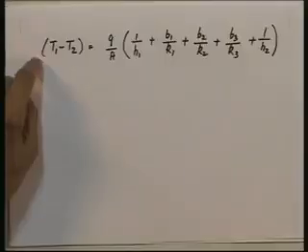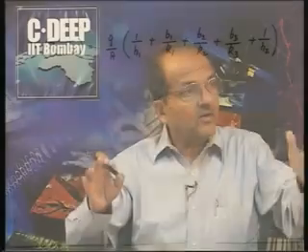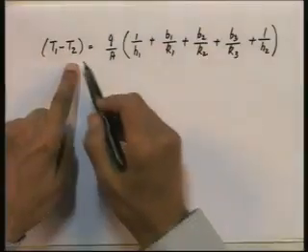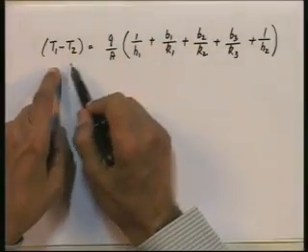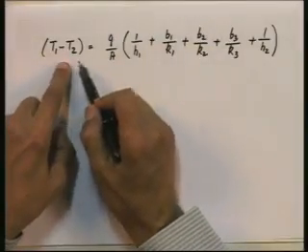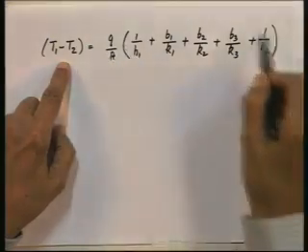And now compare this with my definition of thermal resistance for a composite situation. What will it be? The thermal resistance for the composite situation is given by T1 minus T2 divided by Q. So, if I take T1 minus T2 upon Q to the left hand side in this expression that I have derived here, what am I left with on the right hand side?